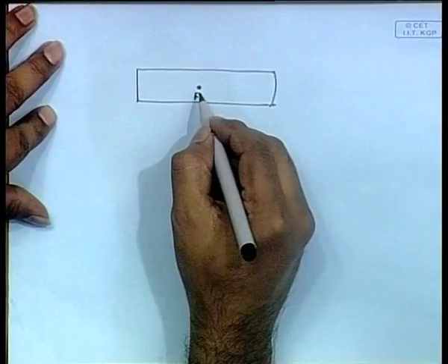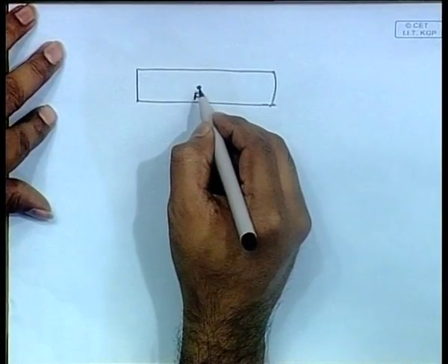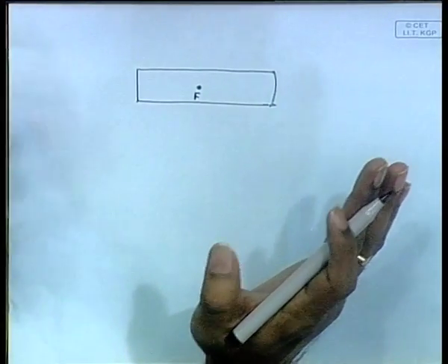That is mainly because of how it trims: the volume aft becomes equal to the volume forward. That is the reason why it trims about the center of flotation. So, every measurement we do here, we do about the center of flotation. So, this weight that we are removing in this problem, we need to find where it is being removed. So, let us look at that.